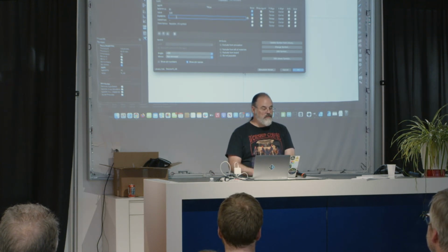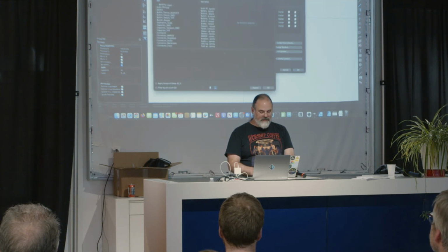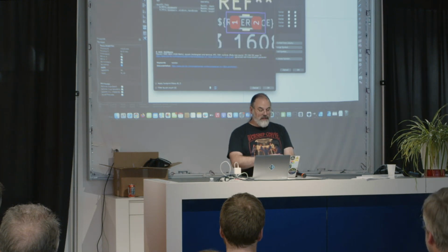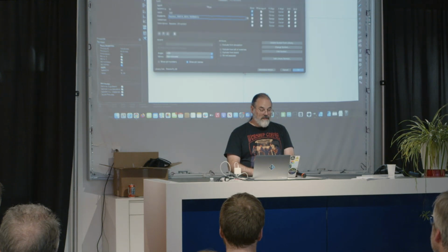I'm not gonna do the math and bore you with all that kind of stuff, but it should be okay. It's not gonna be too bright, not too dim. And I want a footprint, right? I'm going to do a surface mount because I don't want a big resistor on a nice art badge or anything like that. And it's going to go through a pick and place machine anyway. I know that this one is going to be R_0603. They have a really nice naming convention, so it makes it super easy to find this stuff. All right, so I've got my 0603 330 ohm resistor.